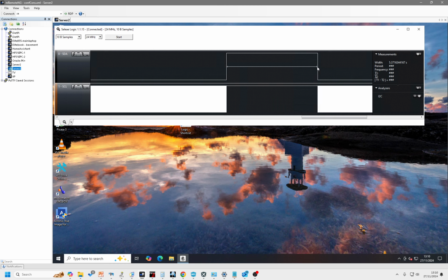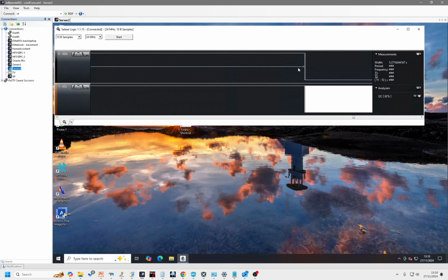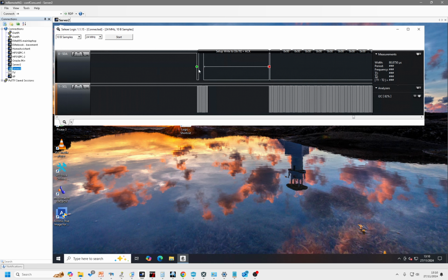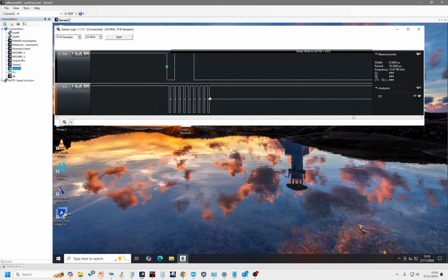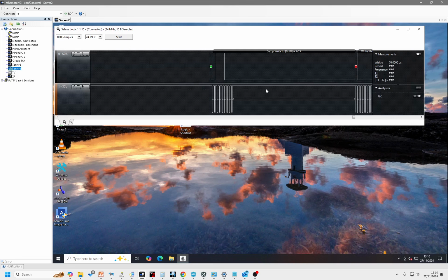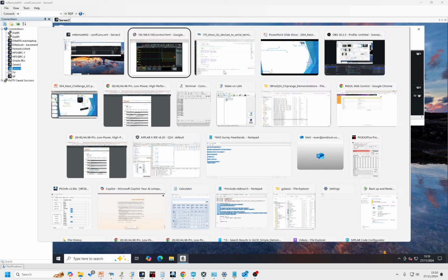And if I zoom in on that event, we will see exactly what we see in the oscilloscope. It sent out, for those who haven't got magnifying glasses, it says 78 ACK. And then it starts streaming zeros. Look at the shape of this. It's got 8 clocks, with a start and a stop at both ends. That's 78 because it's got the right number of bits set. Look, it's got 7 set in the high nibble, and the top bit of the lower nibble is set, so therefore that's 7/8. We know that. We can see that because we're all geniuses, right?